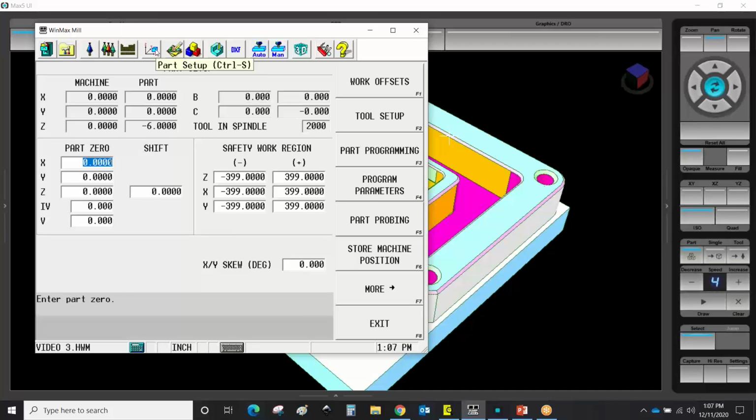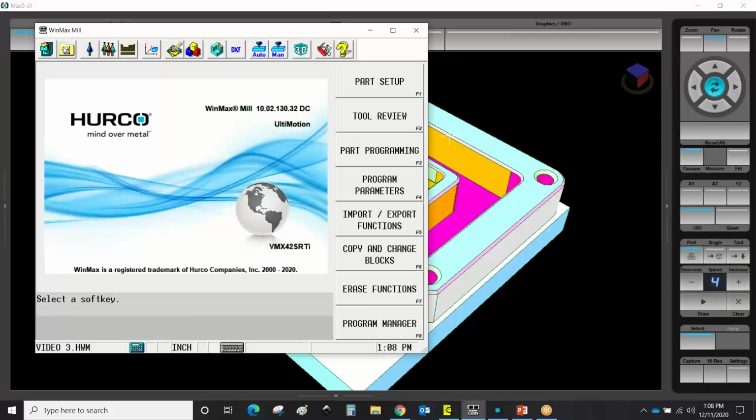Well, there are two things that people will do in that case. They will either create a program called tools, or they would basically create all of the tool list that they're going to use for their machine and then import those into an active program whenever they need to. And that works really well by starting a new program and importing in just the things that I need from a conversational program. However, where that kind of falls apart is if you have made changes.